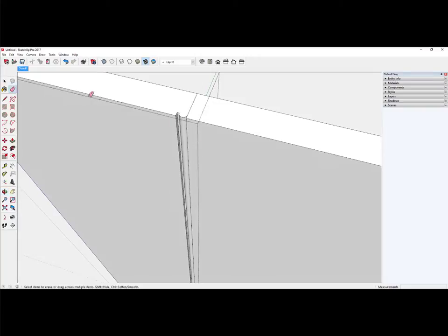Now I need the tongue for the tongue and groove joint. And this is 1 inch thick door, so I'll put a center line at a 1/2 inch, and I would like to have a tongue that is 5/16 inch wide, so I'm coming off 5/32 with the guidelines.